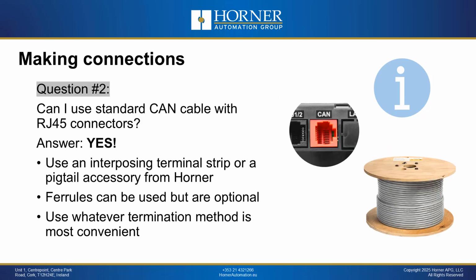The other question we get is, can I use traditional CAN cabling with an RJ45 style jack on my controller or IO drop? And how do I do that? And again, the answer is yes. There are a couple of ways to do that, and we are going to show you in today's presentation.